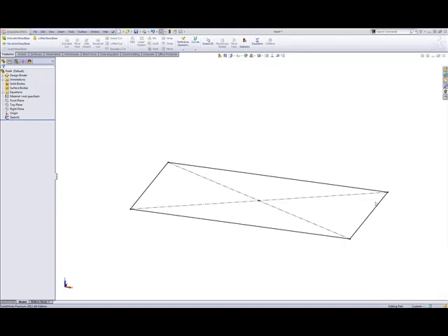Okay, we're going to take a look at setting up a template with some global variables in it. Some standard stuff like, in my case, draft on a part, so it'll be outside draft, maybe radius size, wall thickness or shell thickness. I kind of got one started out here already, and we'll just add a couple more. So my part draft is equal to 2.